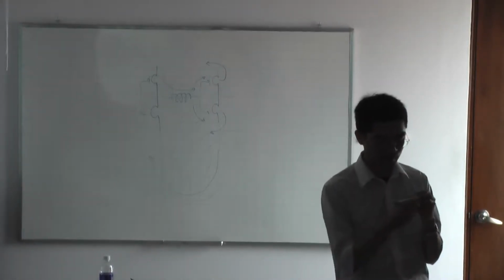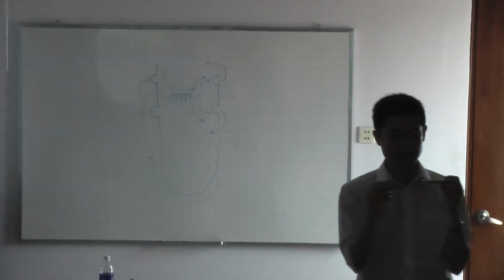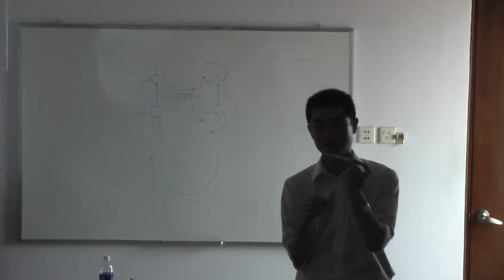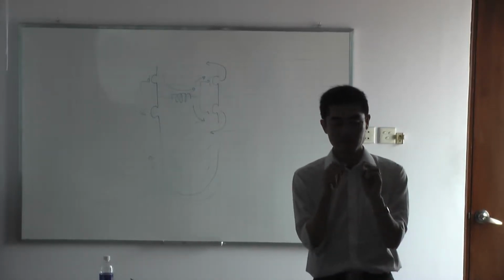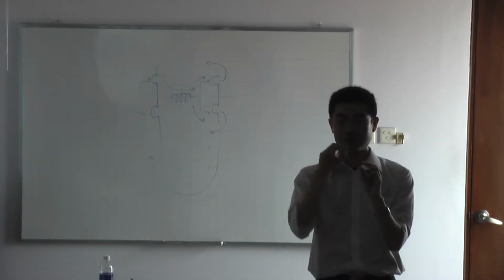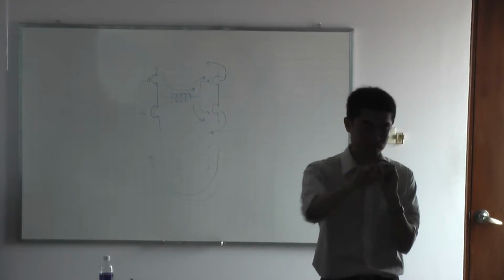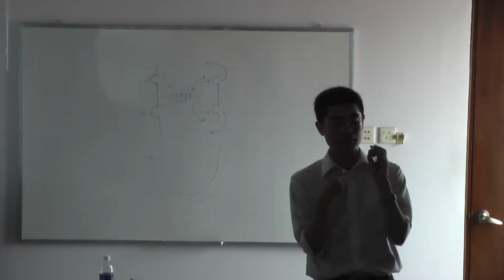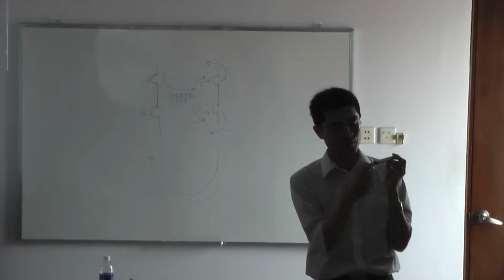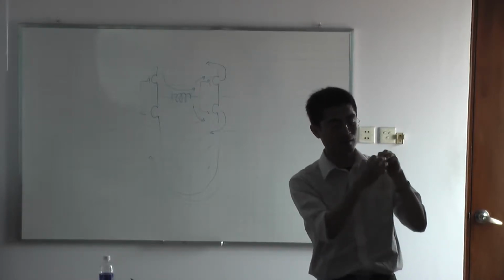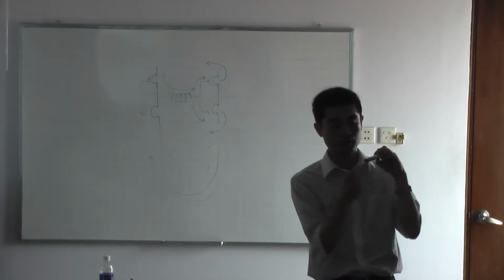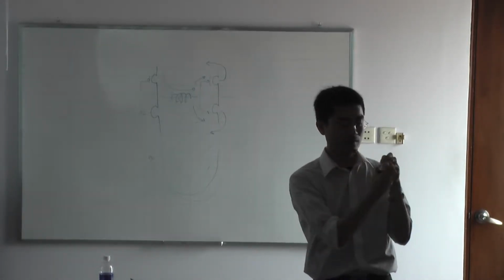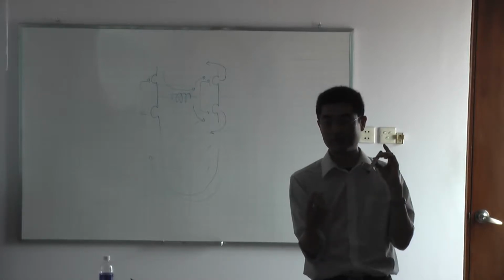And the SMA cable is a very high-speed cable, so this has to be very stable. And when the current goes out, the same amount of current has to come back. So in the SMA cable, there is a center line and there is a shield line, and the center line is the signal, and it is surrounded by a ground line.